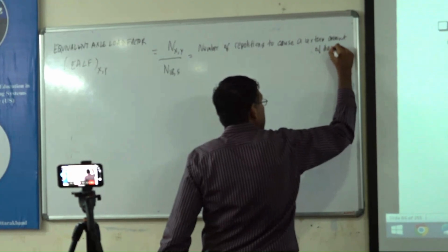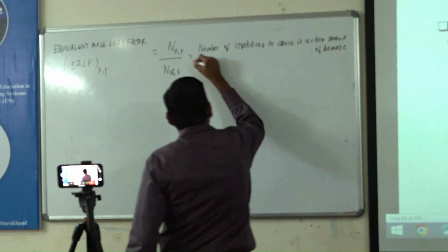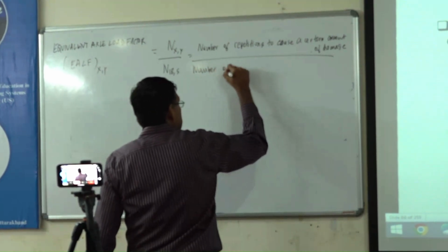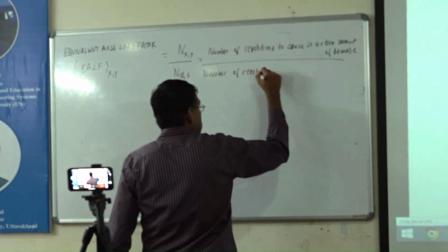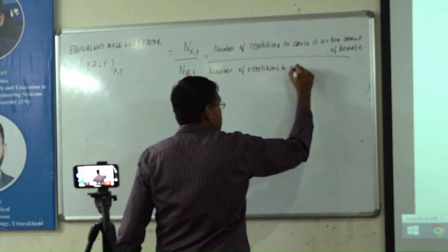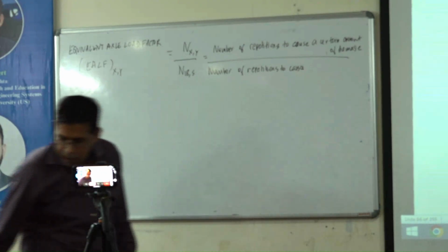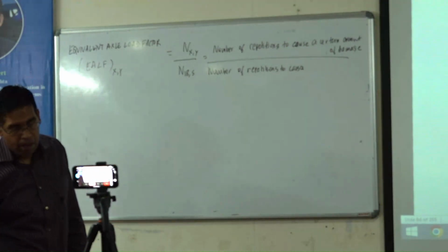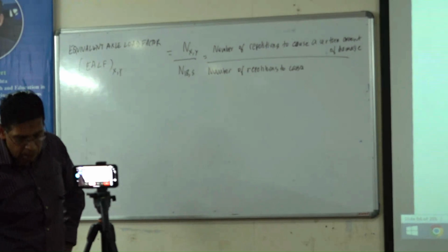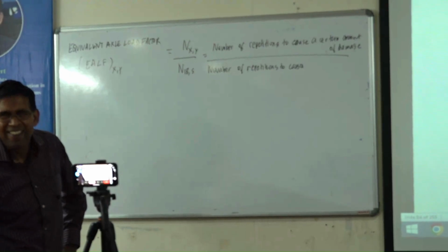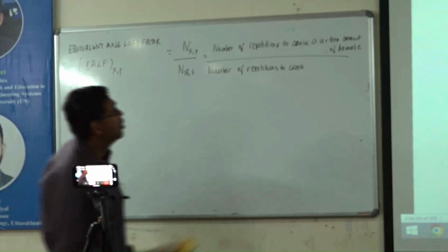I have one doubt. Yes, please. Go ahead. Sir, when we are considering the single axle part, this damage of 1.0, so this 18K came as the maximum axle configuration at that time. So when this has increased, it is actually causing damage more than 1 at present. But still we are considering damage as 1.0.